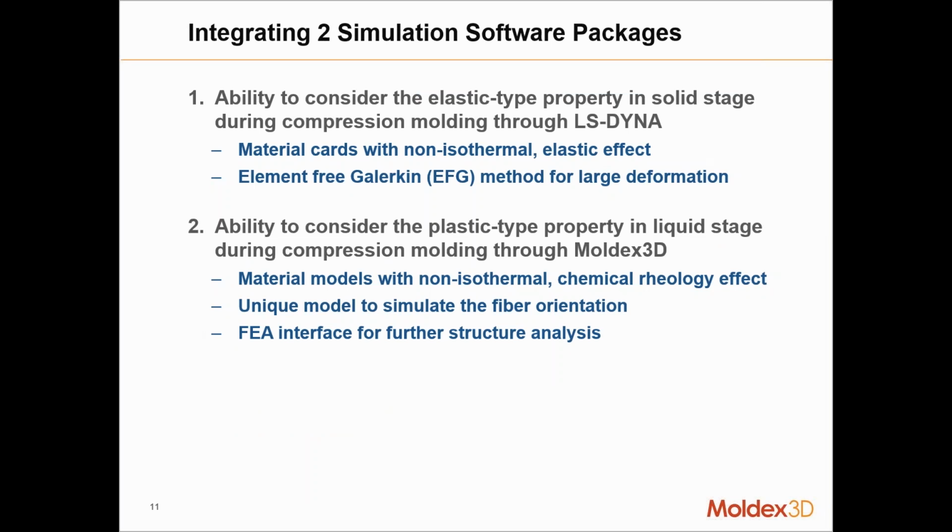So, integration of two simulation software packages. Here we're going to briefly discuss using LS Dyna for the draping. Using LS Dyna, there is the ability to consider the elastic properties in the solid stage of the charge during the compression molding, before the material is fully compressed and in what we call flow.